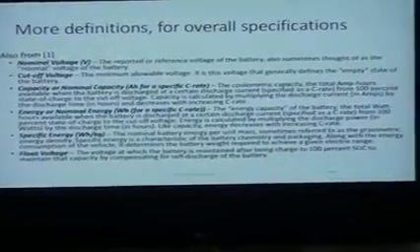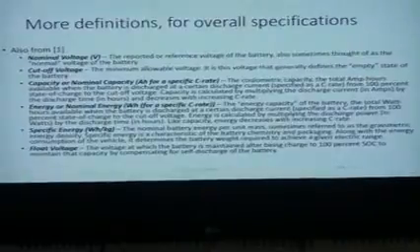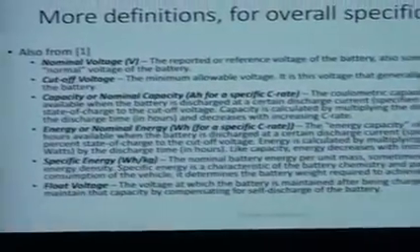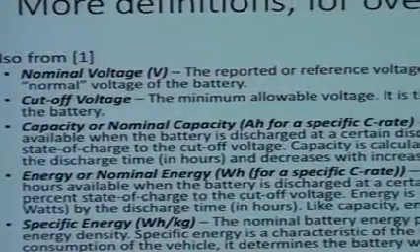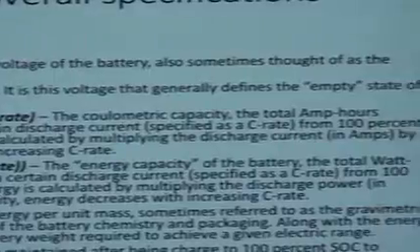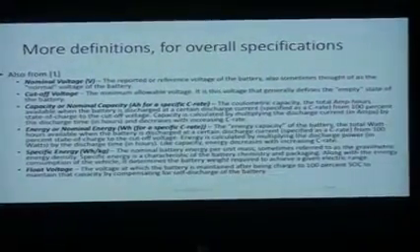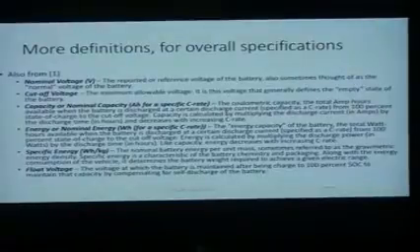The cutoff voltage is the voltage at which we say the battery is empty or fully discharged, right? And so then, even though it's a finite voltage, you might think, well, maybe when it's fully discharged, there is no voltage, but that's not correct. In fact, there's quite a bit of voltage when it's fully discharged. It just can't produce any current, and then there's a big drop off. If you tried to draw more current out, what you would be doing is irreversibly reacting the inside of the battery with itself. There'd be side reactions that would happen, and you would have a dead battery after that, permanently dead.